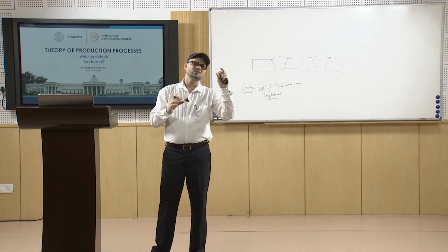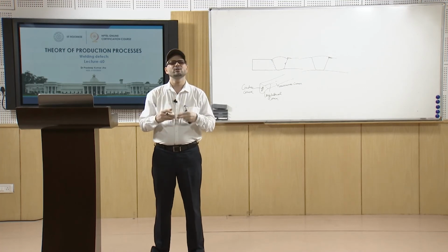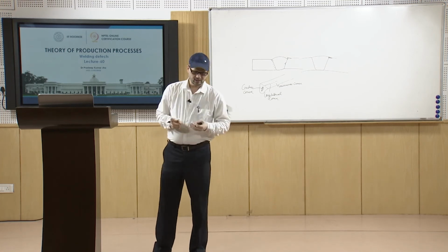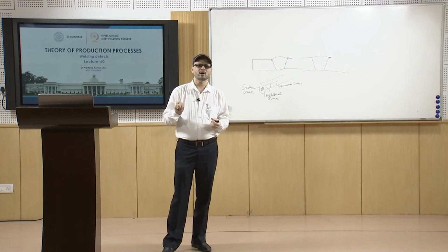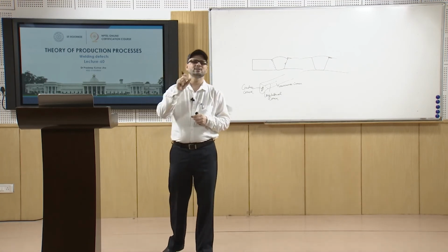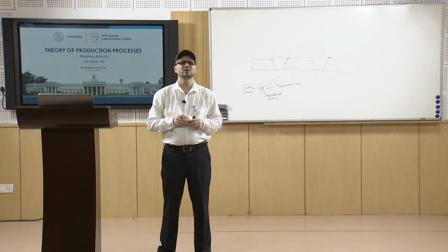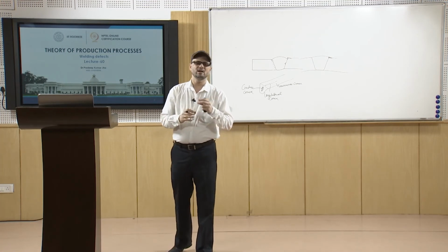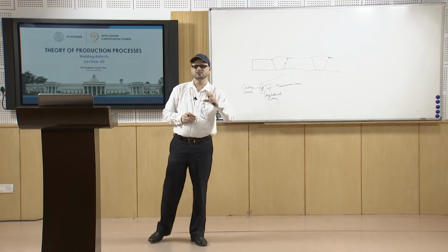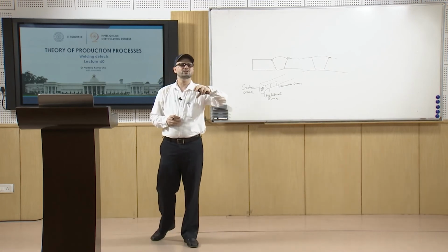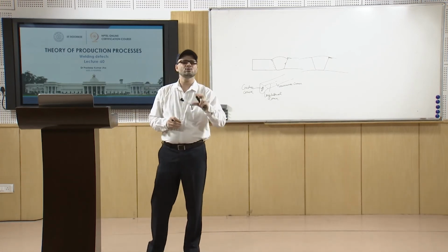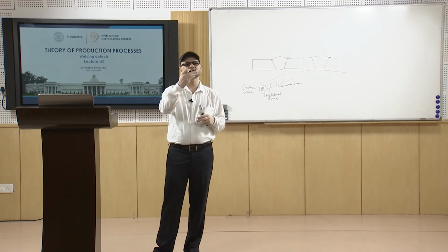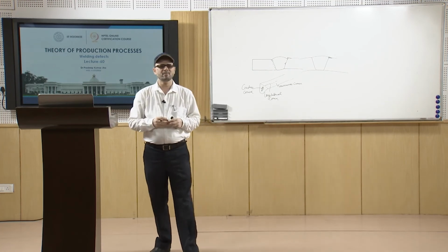In the cavities, normally what happens is that when you are doing the welding, if you have moisture left, in those cases also there are chances of gaseous pockets which are normally trapped in. So, that may lead to cavity formation inside. You may have shrinkage, also shrinkage of the metal which is taking place, and from that also shrinkage cavities may be generated. Solid inclusions, as we have already discussed, if it is not properly cleaned, in that case the solid inclusions may come up.